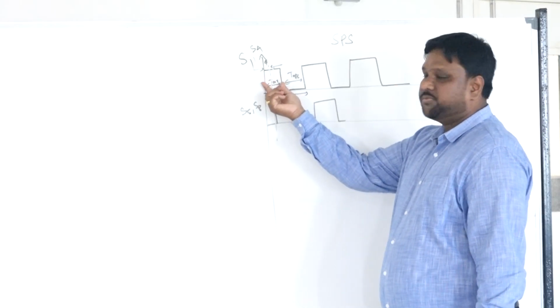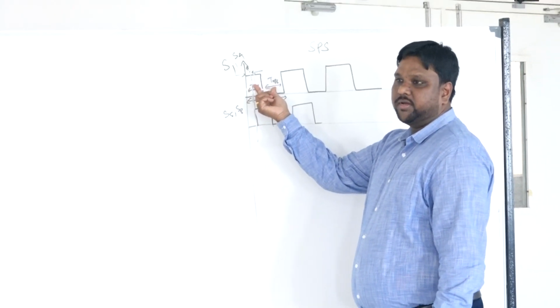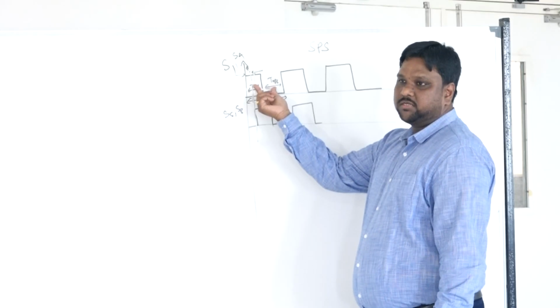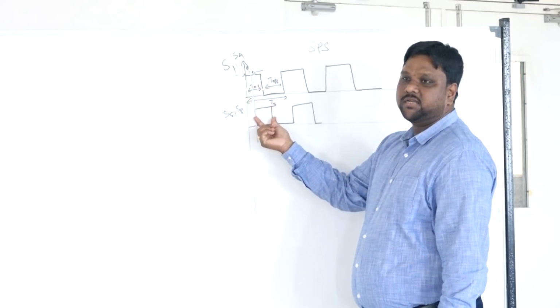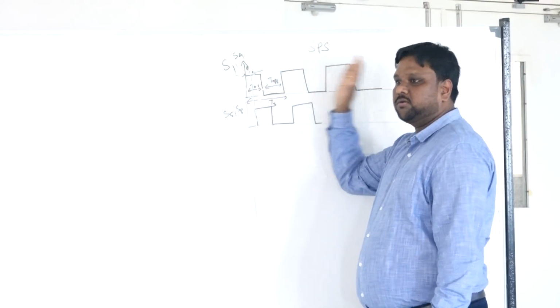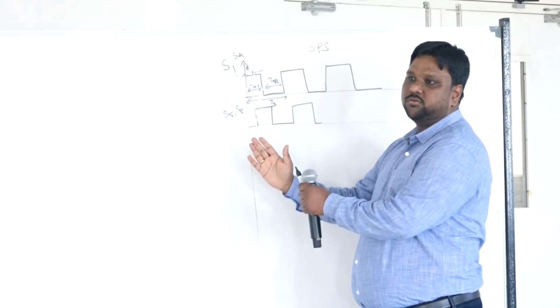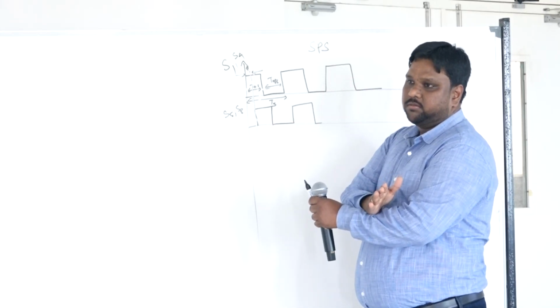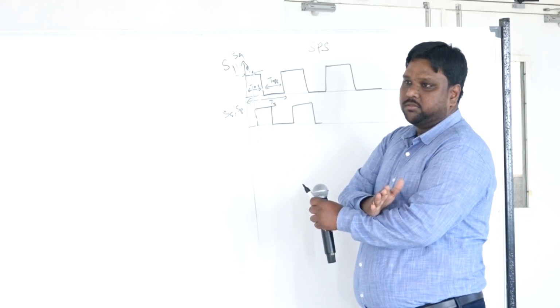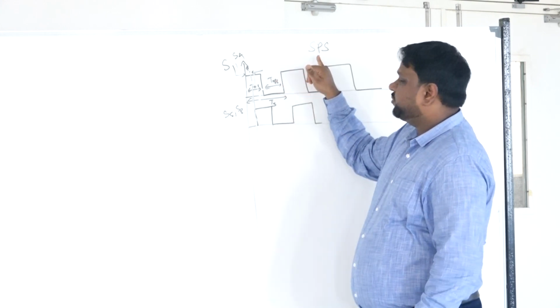I initially shift this with a phi 1, let's say, the S1 S4, and S5 S8 I will again shift to phi 2 with respect to phi 1. So my primary is shifted, secondary is shifted with respect to primary. That is called dual phase shift. Okay, but here we are keeping single phase shift.